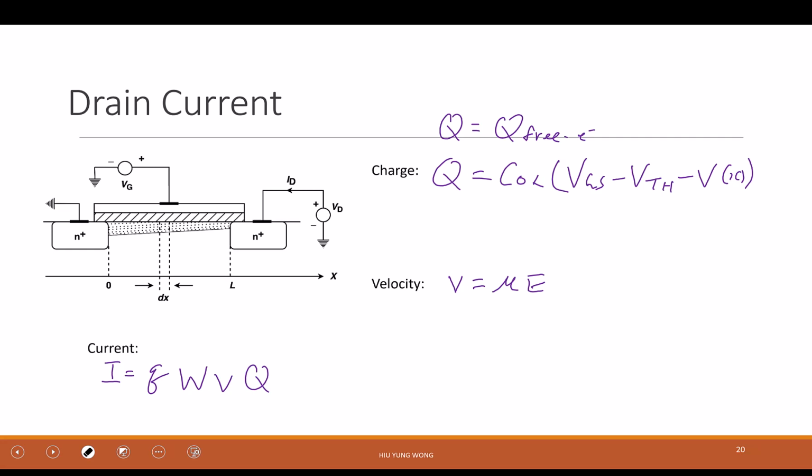We are not talking about electrons in free space. In free space, you just use F equals ma. You know how fast they move, right? So electric field is the force the electron feels, and then it has something called mobility. Some materials have high mobility, some have low mobility. Gallium arsenide has high mobility. That's why they use it for RF applications. You just trust me about this.